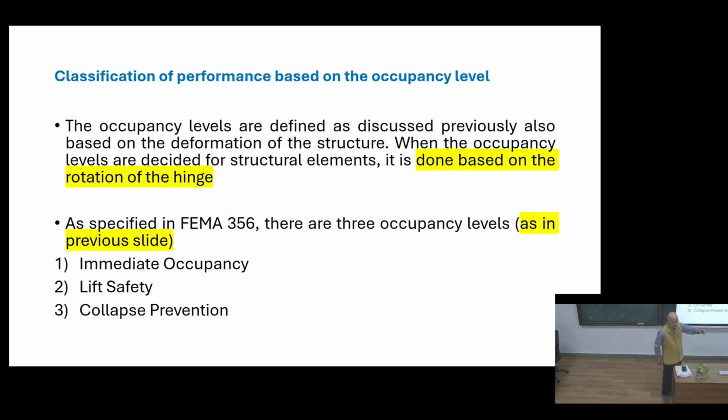An example I said is the door, which has a mechanical hinge. A plastic hinge forms in the structure when the load comes in. A plastic hinge has a certain moment capacity. Yes, okay, you come close to that. That means a plastic hinge forms due to moment only. So a plastic hinge means that at a certain level of moment it rotates, whereas the mechanical hinge has zero moment; it cannot take any moment. That is the major difference. So both are hinges, but there are differences.